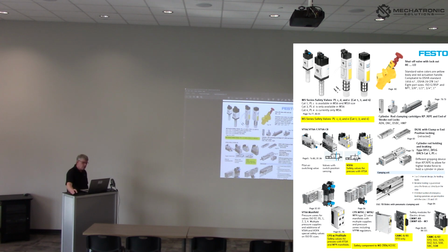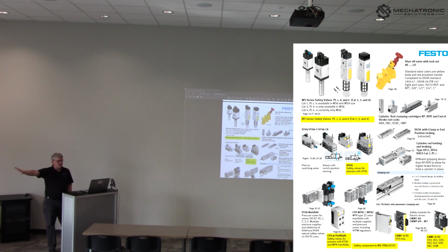With this one right here, you can get to a performance level E by adding another switch to the side of it. But all the safety logic is outboard of that, external, where the E is all built in. So you just tell it on, it does all the monitoring for you. If it's not happy, it just doesn't come on.